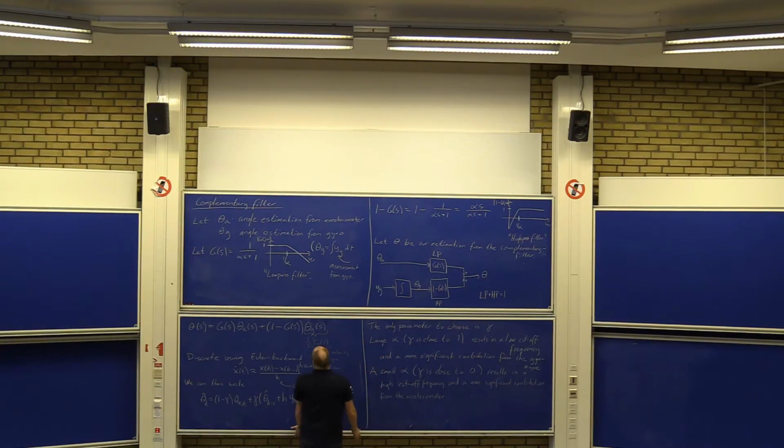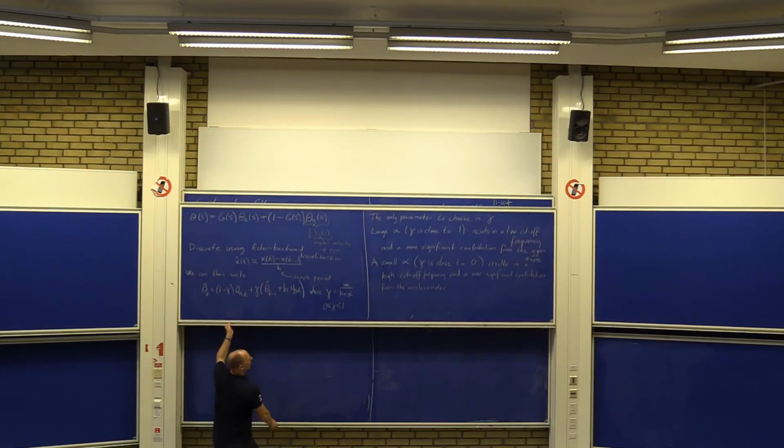Can I ask one thing? Yes. For the accelerometer estimation, we should do 2 integrations, right, in order to get that value. No, we do it exactly as we did before, right? So we had the forces, and then we take the arctan2 on these measurements. So we'll get it directly from there. Okay. No integration required. No. So that's a good thing. Avoid integrations completely. Good.